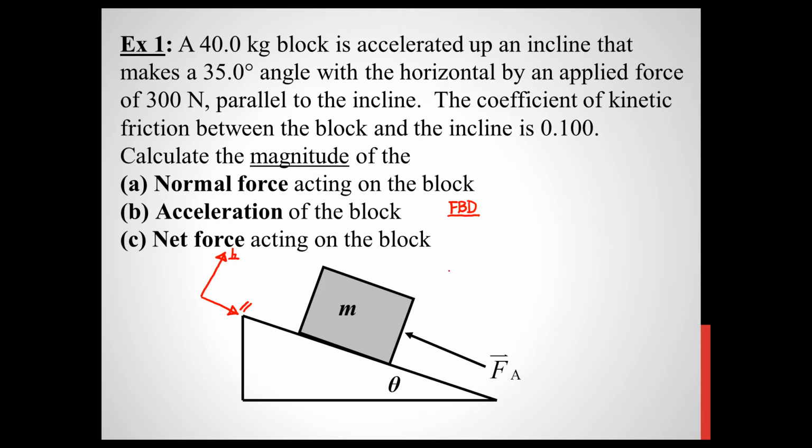Now, on a free body diagram, you're not supposed to show the other objects that your object of interest is in contact with. So I'm not supposed to show the actual incline, but I'll do a line right here just to represent it for the time being. And then maybe later on I'll erase it. And actually, maybe right now I'll just do it in a different ink color. I'm going to heavily exaggerate the angle. Theta. And I'll also do it for the mass acceleration diagram, which I'm going to deal with in a moment.